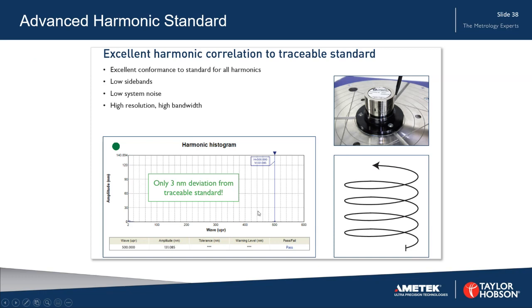But that's not just the important thing. The important thing is here that there are no other harmonics shown. There's no sidebands, there's no energy from these harmonics displaced onto other harmonics, and that's a very good indication of the quality of the instrument that's doing the measuring.